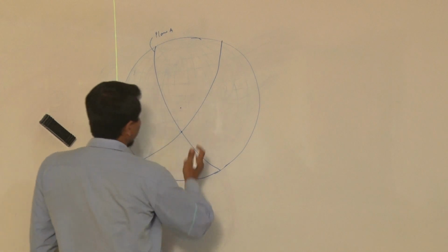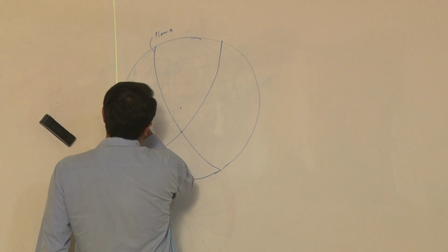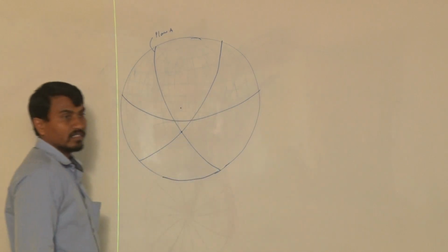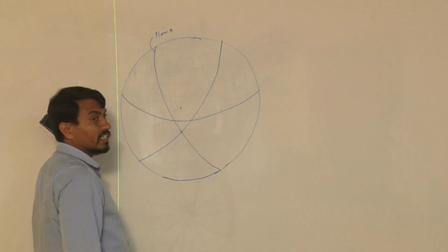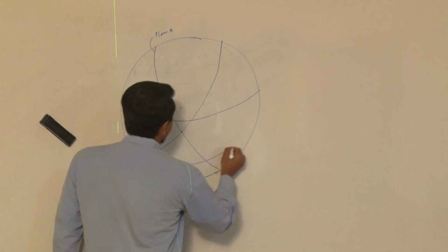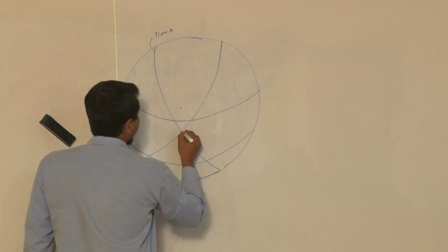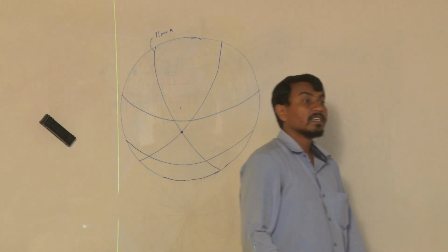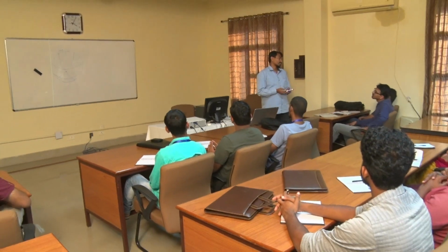So there is a condition that this line, suppose there is a slope face orientation like this, and if you equally plot, suppose 30 degree your friction angle, 1, 2, 3 like that, from the center, then your line of intersection must lie between the slope surface great circle and the friction angle. So this is an easy problem to solve using the great circle.